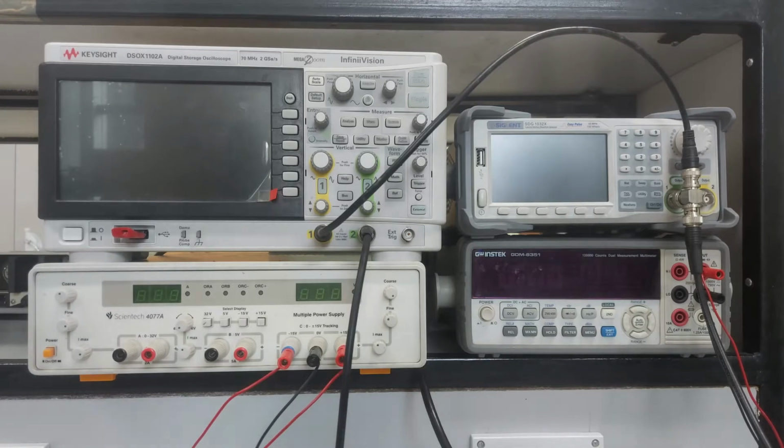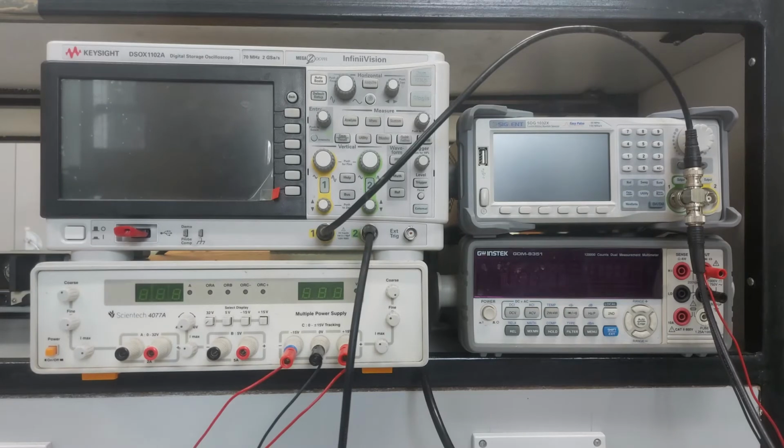So in the case of a practical op-amp, that is the real op-amp, bandwidth is finite, gain is finite, but very high. In the ideal condition, input impedance is infinite, but we have a very high one, that is 2 mega ohm, and the output impedance should be 0, but we have some finite value, that is 75 ohm. So we can use this op-amp in place of an ideal op-amp.